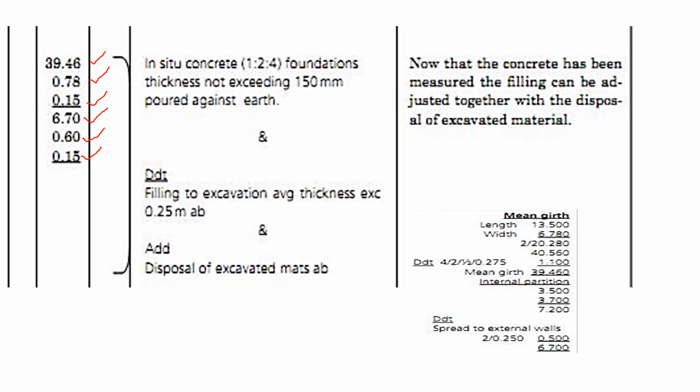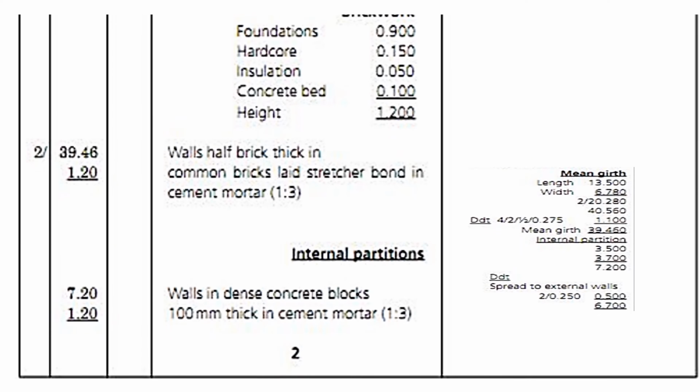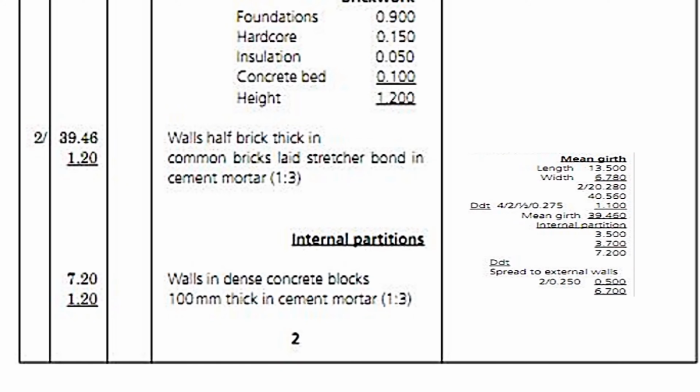For that volume of the concrete, remember that we assumed that we have refilled the foundations. So that soil was taken to refill and ram. So that soil, because now it has been replaced by the concrete, we shall deduct it from refill and ram, feeding to excavation. Then we shall add it to cut away, the soil that will be disposed away from the site. All right. So to brickwork.